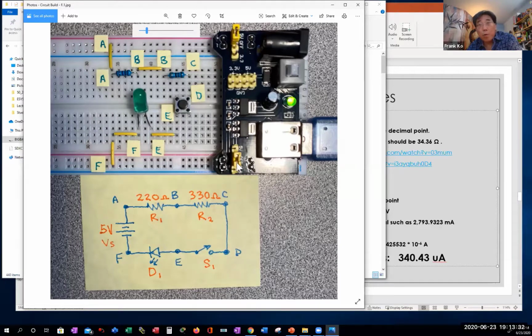The lower jumper wire here is in the off position, so we're only using a single 5-volt source, which means I'm powering the red rail with this. That's where the positive side of the voltage source is sitting. That's point A, and it's also where the resistor connects to power. So point A is on the rail itself, as well as this side of the resistor.